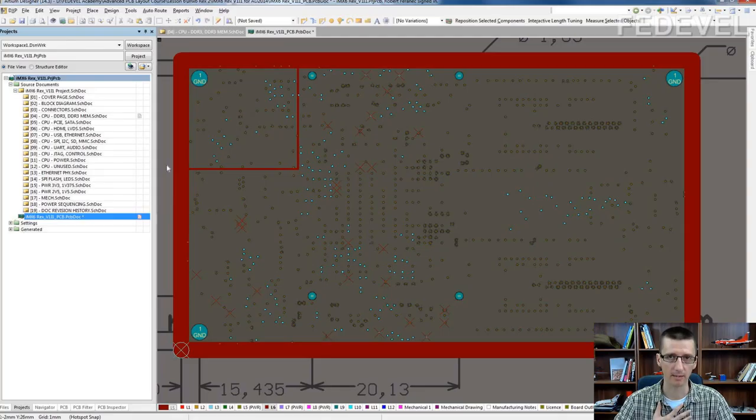Normally for my designs, if I need to draw different powers on one layer, I use a signal layer. Normally in my designs, all the power planes are just one net. I don't split power planes. Why? I just find it simpler to work with polygons. Polygons are the power planes which are placed on a signal layer. I'm going to show you.